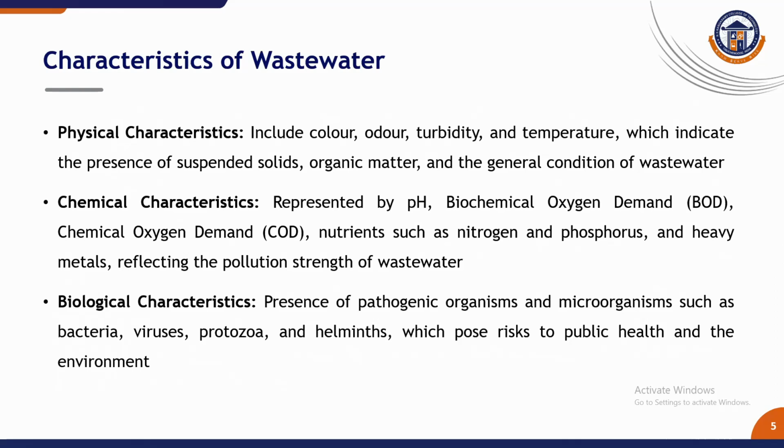The characteristics. To design a treatment system, it is important to understand the wastewater characteristics. Physical characteristics include color, odor, turbidity, and temperature. These indicate the presence of suspended solids and the general condition of wastewater. Chemical characteristics include parameters such as pH, BOD, COD, nutrients like nitrogen, phosphorus, and heavy metals. These indicate the pollution strength of wastewater.